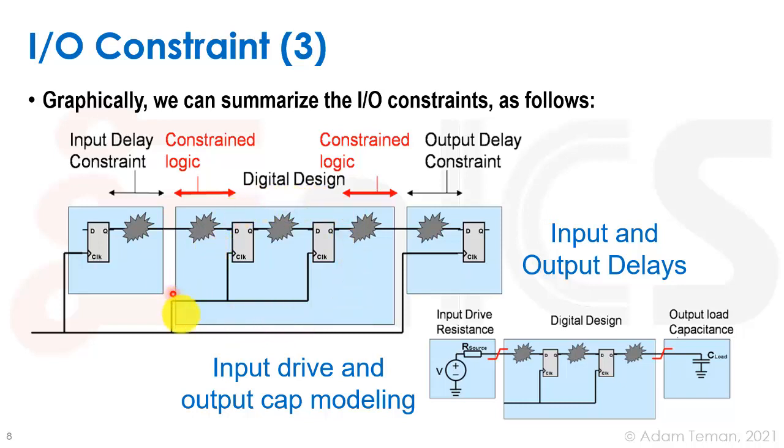And life would be, I guess, beautiful if all we had to do was just optimize these reg to reg paths, because we really know everything about them. But it's not. We have other people we have to talk to. That's how the world works. And so there's going to be some sort of a timing path outside, both on the transmitting and on the receiving end of our macro. So basically, we need to model these parts because they don't exist.